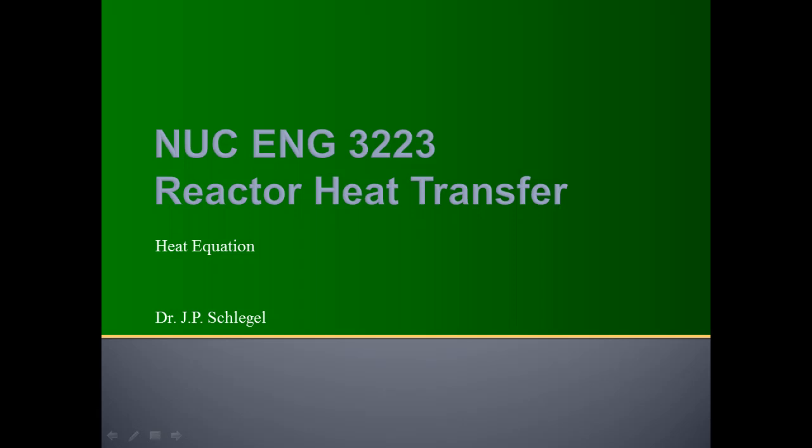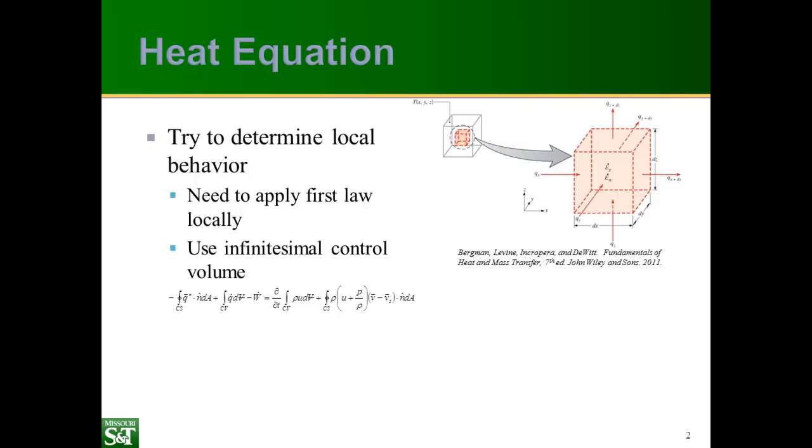Hello, we're going to talk today about the heat equation, which is also known as the conduction equation. The goal here is to try to find the temperature distribution in a solid. So we're going to apply the first law locally over this tiny, what we call infinitesimal control volume, which has dimensions of dx, dy, and dz. To do that, we're going to start with the first law.